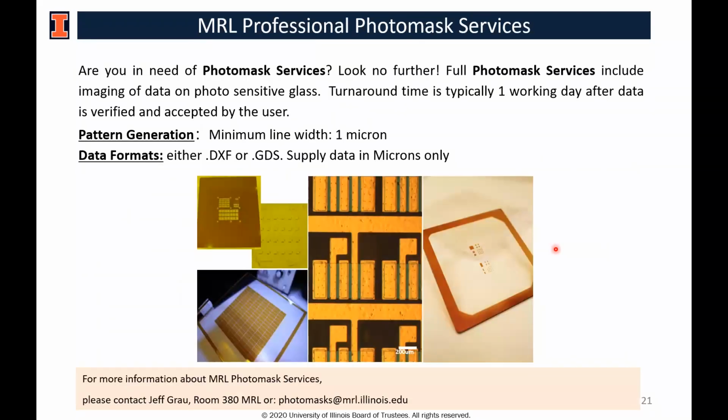We do offer here at the MRL professional photomask services. If you're in need of a photomask, we do ask that you supply the data in either DXF or GDS format, and we also ask that you supply your data in microns only. We are able to achieve a minimum line width of about 1 micron. If you're interested in any of our mask services, please contact me, and I'll be more than happy to accommodate your request.